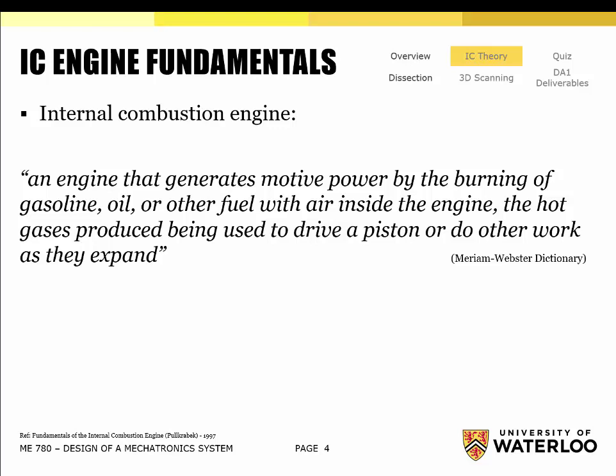So what is making the work, or what's generating the work? The hot gases produced are being used to drive a piston or to do other work as they expand. Okay, so from a very simplistic point of view, I always want you to connect what we're talking about subsequently to this idea of a combustion process producing hot gases. Those hot gases create pressure when contained, okay, and that pressure when pushing against a surface can produce a force. Okay, that force is useful to us because we can convert it into a rotation, which is then a torque. Okay, so this is very critical in just unpacking and dissecting this definition.